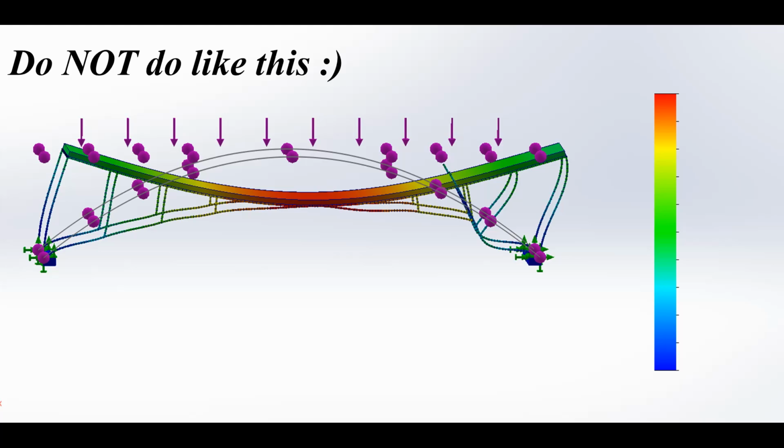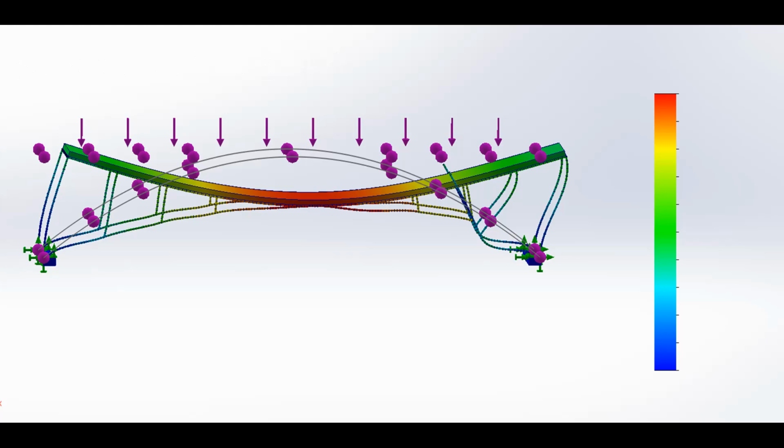And you can see here that the vertical columns aren't just compressing, they are bowing out in an S shape. So, as I figured out, this is a classic example of Euler buckling. The members were simply too thin to handle the given load. So this is an excellent case study for students, and this was an excellent case study for me, demonstrating that geometric theory must always be validated by stability analysis.